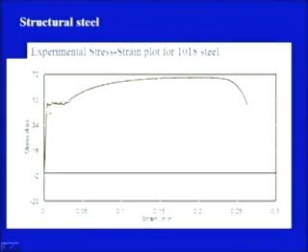So again, we can clearly define the stress and strain. Up to this point is the proportional limit, this is my yield limit, here is the lower yield limit and the upper yield limit, and this yield plateau remains almost constant as you apply the load. Then the hardening region will come, up to this point, which is my ultimate tensile strength. Because of the lower carbon percentage, immediately after the maximum tensile strength it will go for failure. So, this is the rupture.